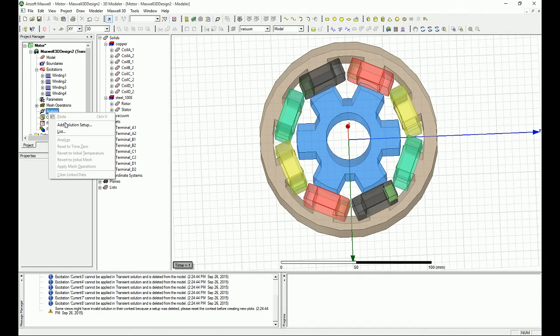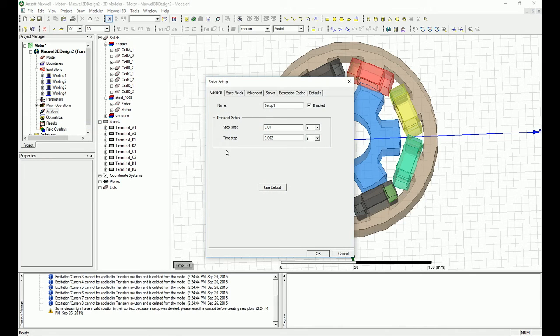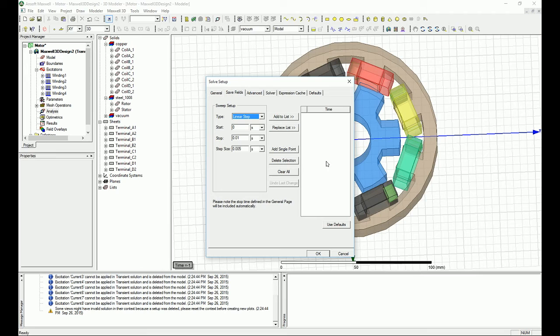And lastly, you need to assign an analysis. The analysis that we have here, you can say, okay, we have a start time and a stop time. The stop time can be 20 milliseconds, for example. This is 20 seconds, and you can select 20 milliseconds. And the accuracy, you can leave it at 2 milliseconds. You can make it 1 millisecond, but it basically takes a lot of time to finish. Let me just tell you four other things here that are important.